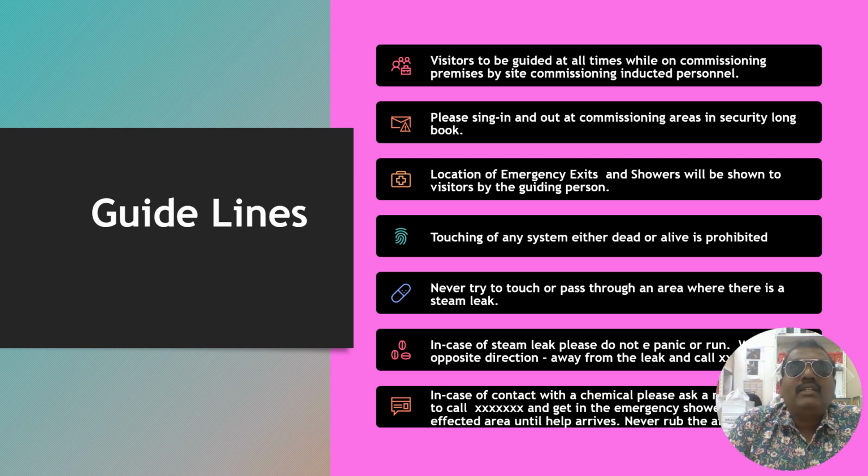Touching of any system, either dead or alive, is prohibited. Never try to touch or pass through an area where there is a steam leak. In case of a steam leak, please do not panic or run in the opposite direction away from the leak, and call the emergency contact number. In case of contact with a chemical, call the emergency contact number and use the emergency shower on the affected area until help arrives. Never rub the chemical affected area.